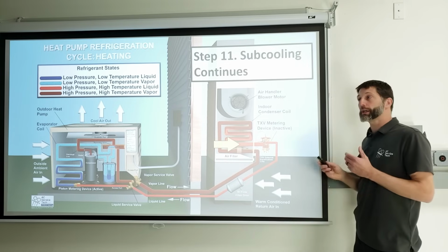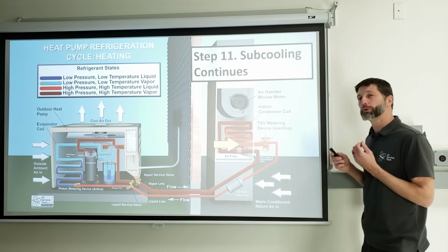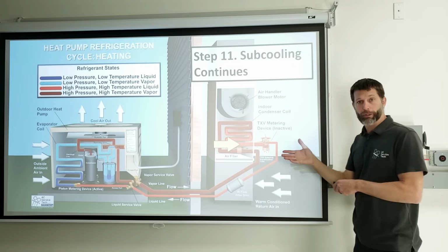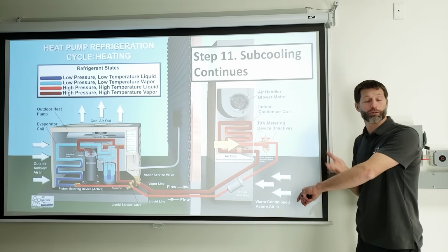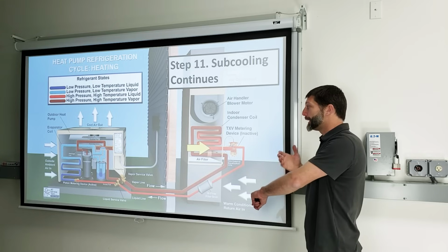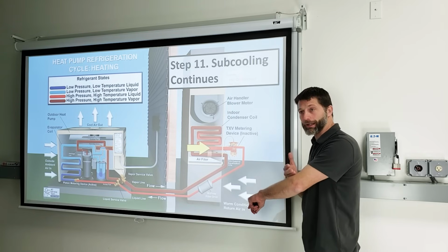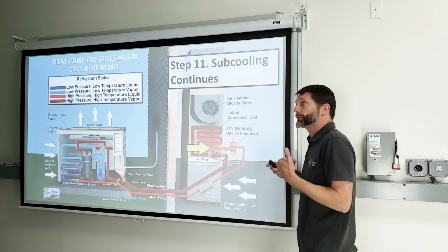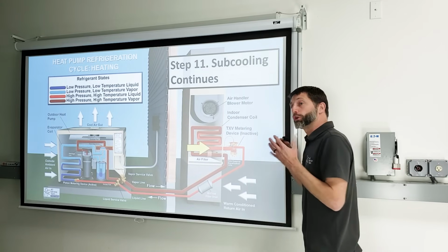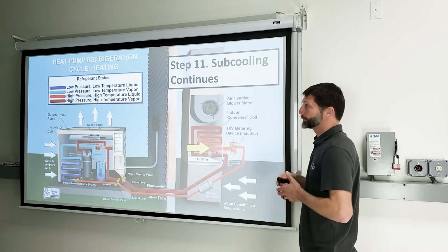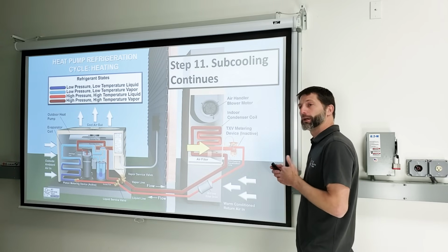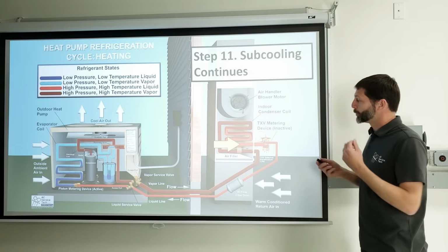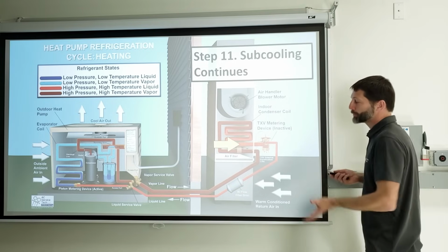So a heat pump may not feel comfortable in the wintertime because the blower motor is going to be at a high fan speed, and it's going to have that evaporation effect on your skin. You're going to have a lot of air moving in the building, and that's going to basically dry your body out. It's going to cool your body, and so that's an evaporation effect. So it's going to make you feel colder. Remember, coldness is just a feeling. We don't refer to this stuff as cooling necessarily because it's not doing that. Cold is a feeling that we have. So we're going to feel a little cold, but the temperature is rising in the building.